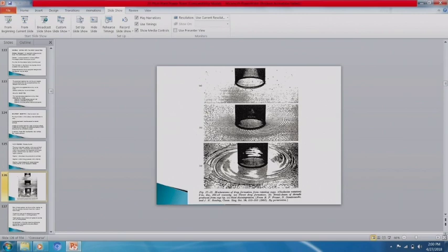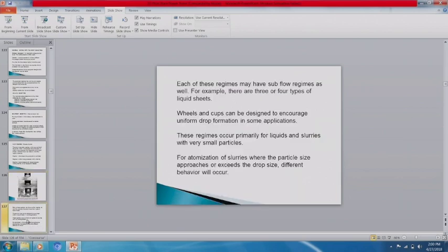Okay. If I was to try to make a uniform emulsion, what I potentially would do is I would run this machine in air. This is being run in air, and then put the droplets through a falling liquid curtain, and eventually concentrate it up, and I would have a uniform emulsion.